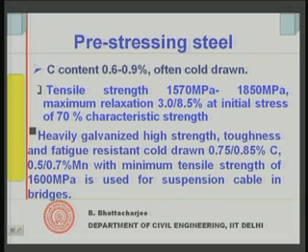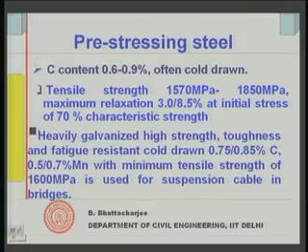Heavily galvanized, high strength, toughness and fatigue resistance. If you are looking at suspension bridge cables, this is another kind of steel which has to withstand high tensile stresses, that is, it must have a high tensile strength. The suspension cables of cable suspended bridges are also exposed to a corrosive environment. Therefore, they are heavily galvanized, high strength, high toughness, right. They should be able to withstand a lot of fatigue, because there will be horizontal movement due to wind.